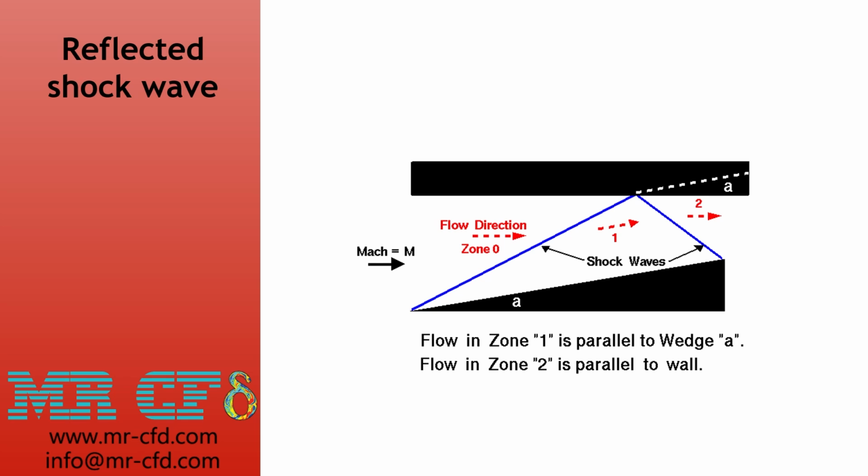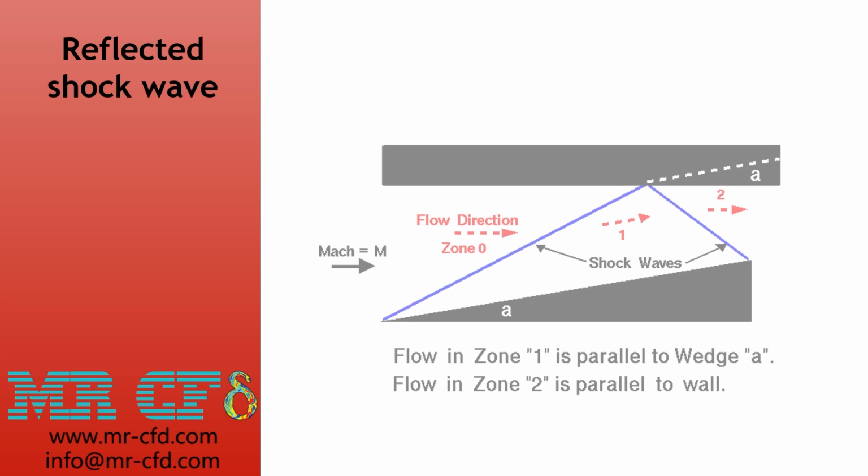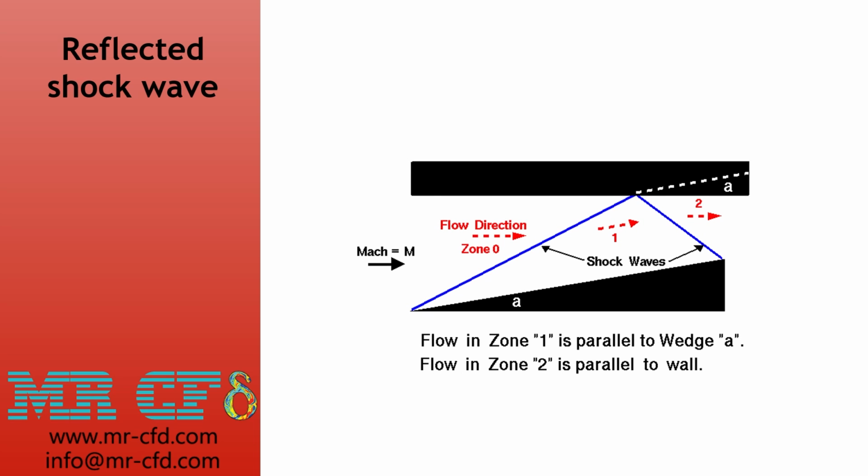So the shock waves can be reflected like light beams inside channels or ducts, for example, an aircraft intake. These reflections can occur for two main reasons. For example, imagine we have an intake for our supersonic aircraft. We want to reduce the pressure and the speed below Mach 1 to give undisturbed air to our turbofan engine.